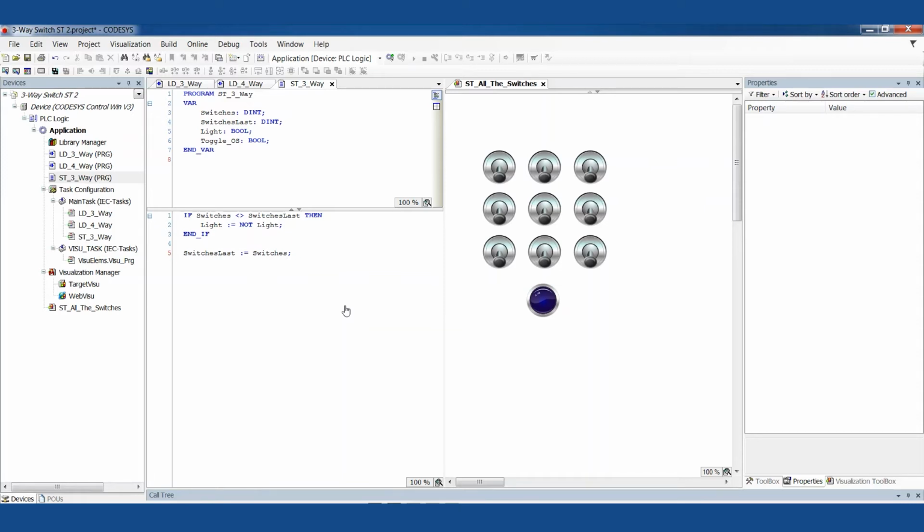In house wiring, we would call those three-way switches, and they're special switches with two contacts in there. It's single pole double throw, the electrical term. If we want more than two that control the same light, we would use what's called a four-way switch. So what we're doing here is simulating that same functionality in the PLC using switches that have a single contact, single pole, single throw. So we only have one input to the PLC from each switch.